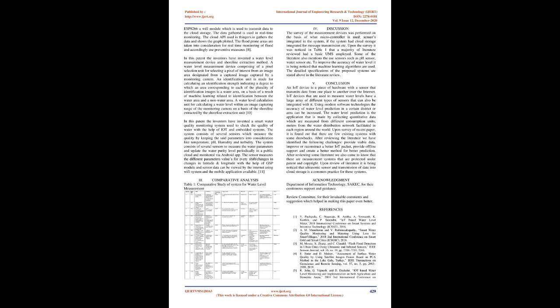The author has used 6 infrared temperature sensors, which help in measuring both the ground temperature in their field of view and their actual temperature. As the raw data generated by the ultrasonic rangefinder and infrared temperature sensors have different scales and exhibit inconsistency, a pre-processing procedure is essential for accurate sensing of floods based on measurement data produced from sensor nodes. Pre-processing involves fault detection and missing data reconstruction. An artificial neural network, ANN, is used to monitor water level in real time as it has excellent accuracy, high precision, and low computational complexity, which makes it suitable for low-power embedded platforms.